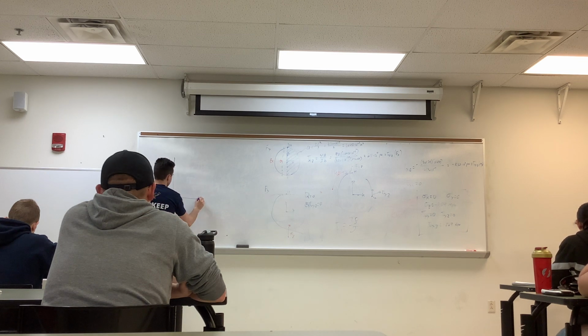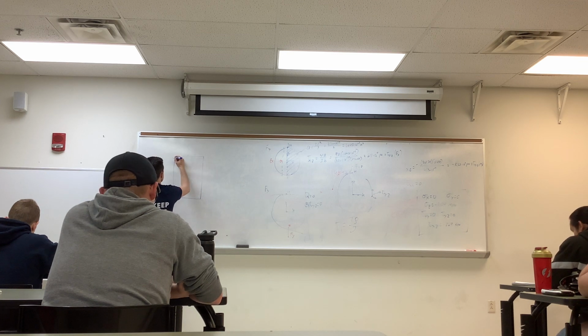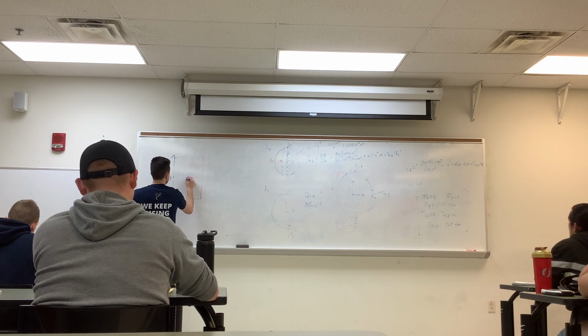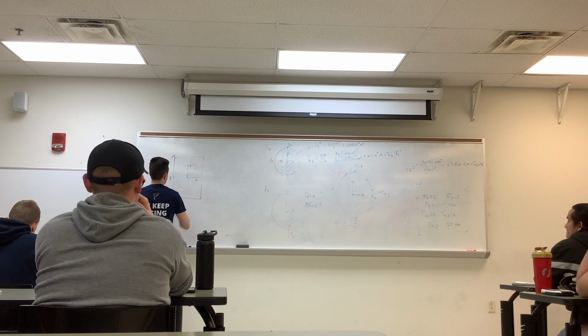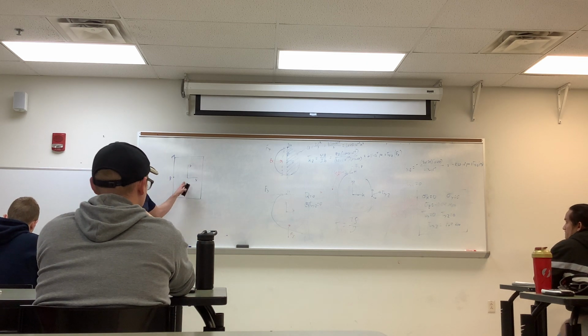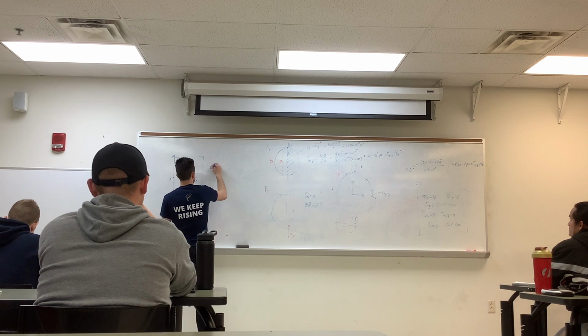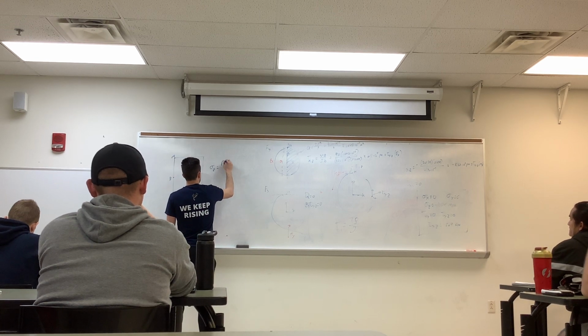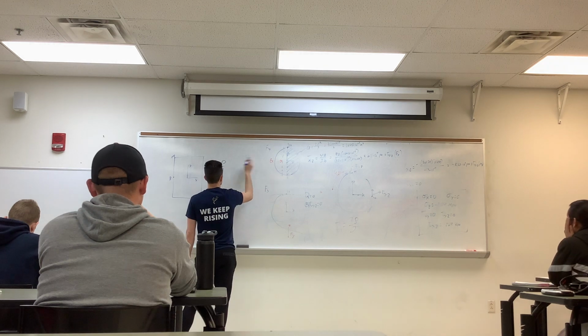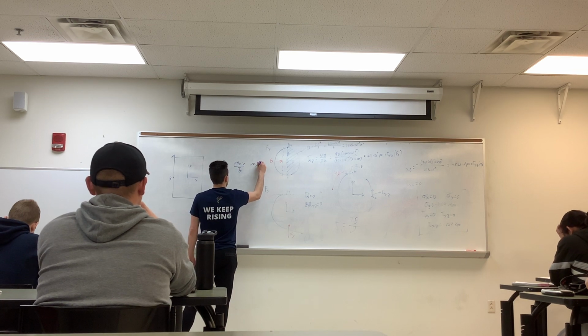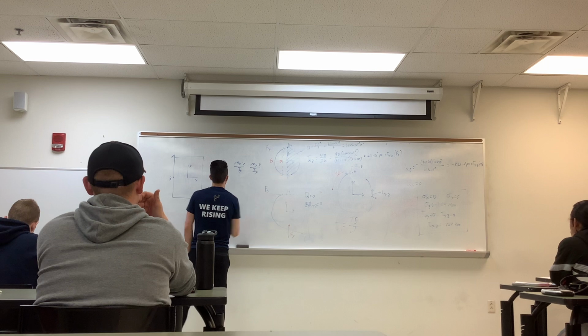When I first introduced combined loading, we had a rectangular cross section. We had a point A, B. We had our axes of X and Y. Does it seem similar at all to when I introduced it? So again we had our Z, so sigma Z here. We had our P over A, or force in the Z direction. We have our moment terms, M_x y over I_x and M_y x over I_y.